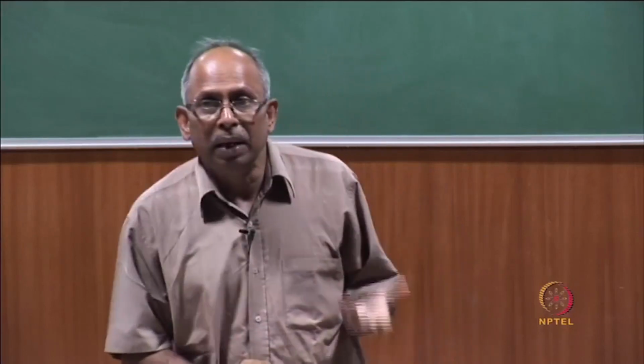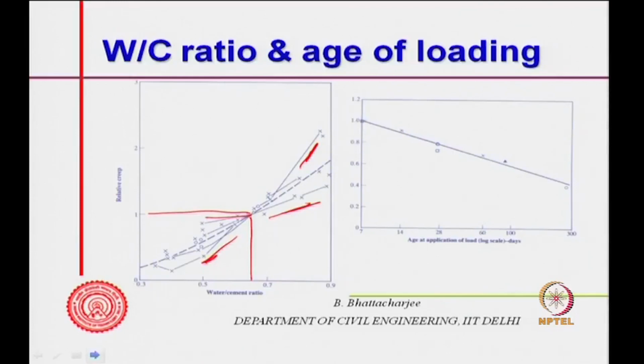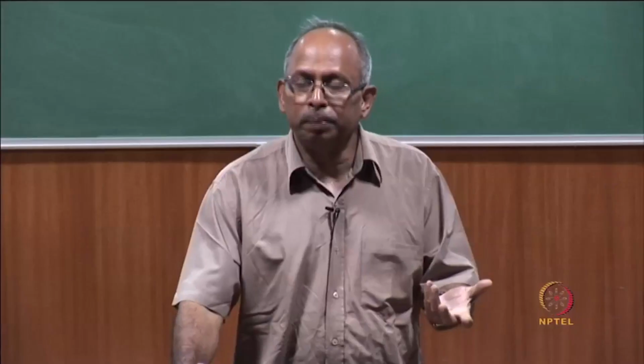It also says that if the age of loading increases, creep should decrease. For the age of application of the load, if it is 7 days, and this is 1, then at 100 days it will be something like 60% of that. Relative creep is on this axis, and therefore we can understand that more water cement ratio means more pores.